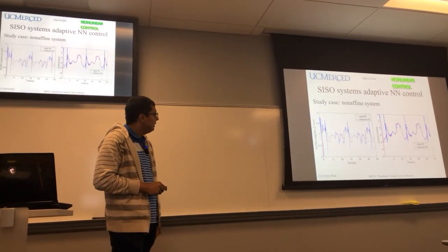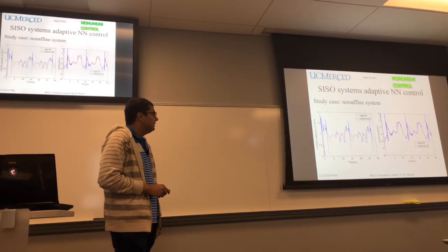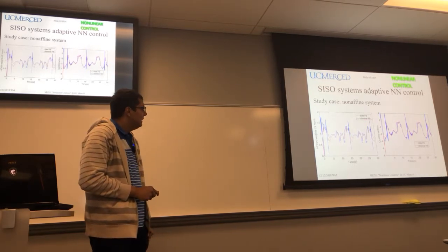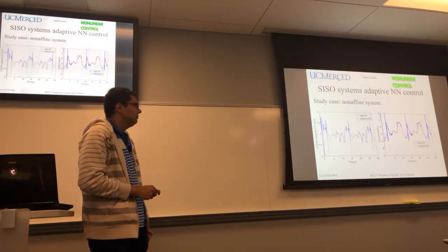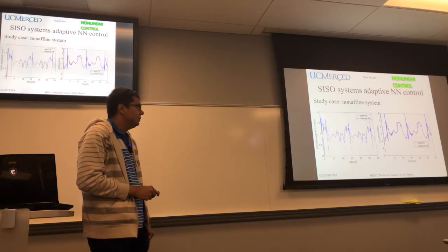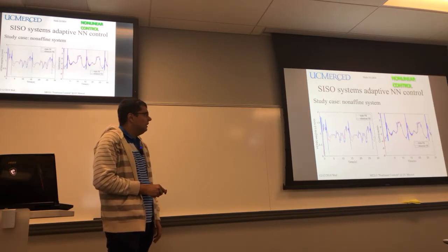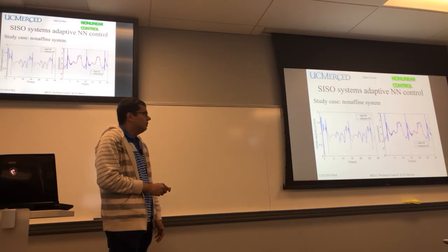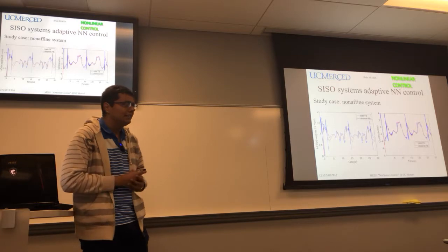The study case, we continue. In this case, the L2 weights. These L2 weights have the state feedback and the observer feedback. Because of the use of the observer, we see more peaks in the estimation than with the state measured directly, so that signal is smoother. And the control action with the observer will be affected by this behavior because it has stronger peaks in some places, but it's because of the estimation.